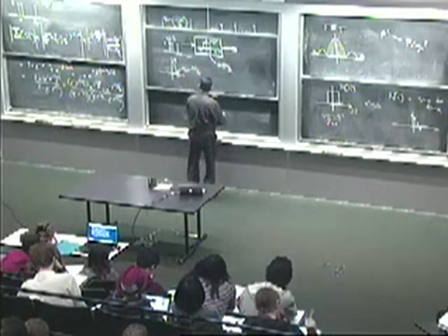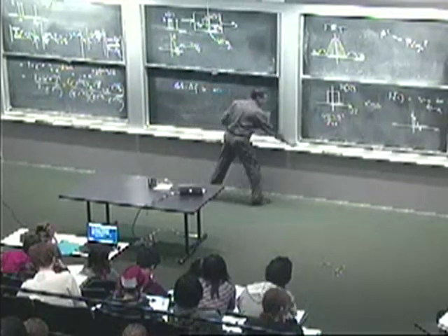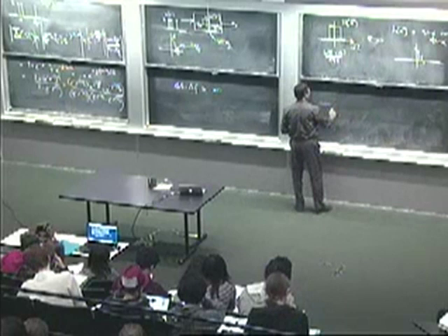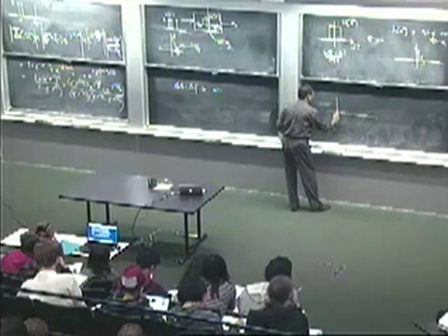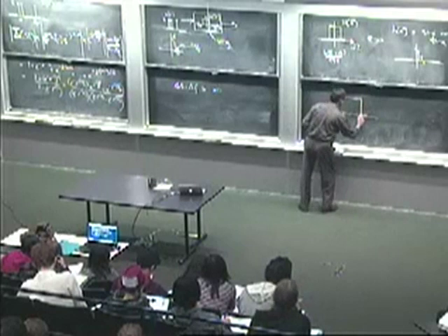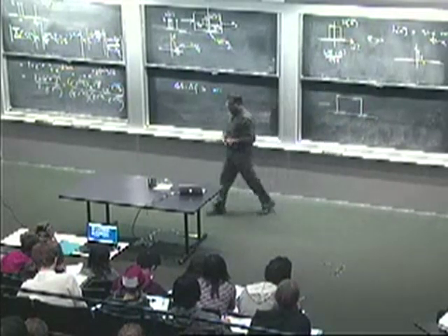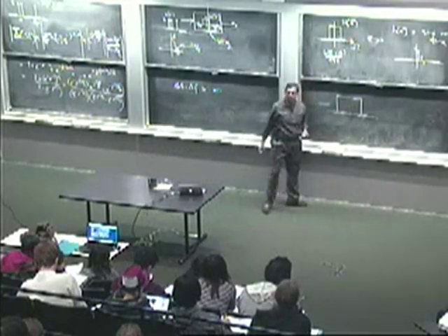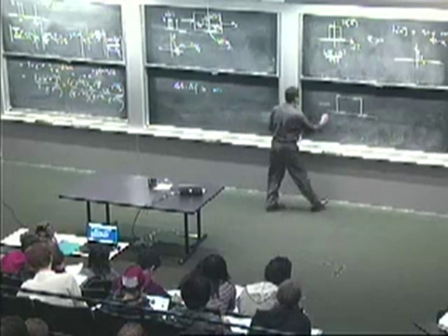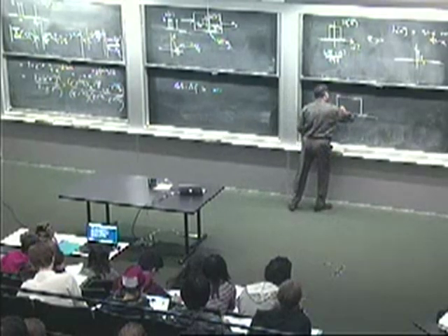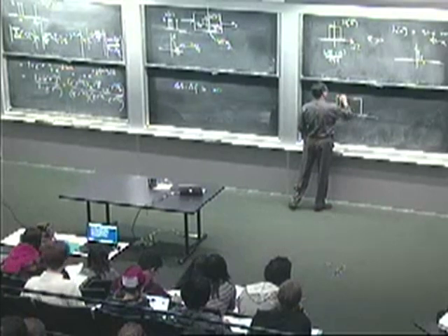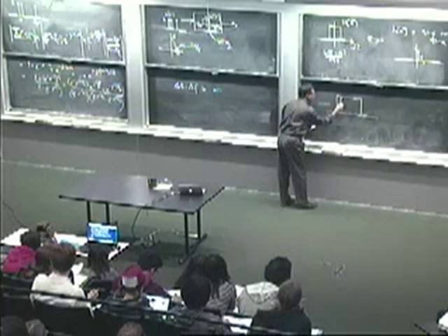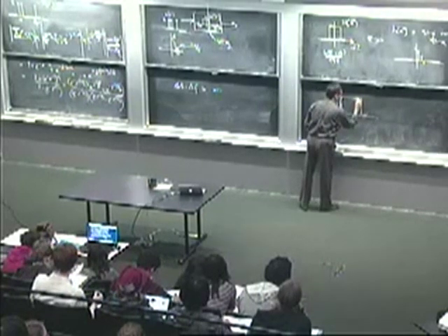So what I've actually done here is, instead of a signal that, well, if you'll permit me, I don't want to draw these stem plots, the lollipop figures, because they get painful to draw, but just assume that this is 256 such things. That's the rectangular pulse we were trying to send before. What I've done now is instead say, well, let me round the edges. So I'm going to have a half cycle of a cosine for that edge. Okay, so these are the samples I'm going to use at this edge. And I'm going to have a half cycle of a cosine at this edge.